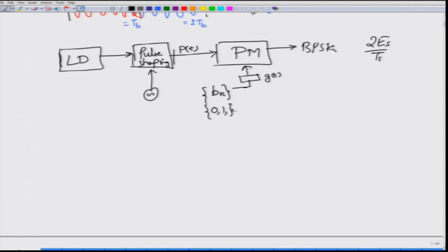Now, with the BPSK signal you are able to transmit one bit for one symbol. So, it occupies a certain bandwidth. We will come back to the bandwidth calculation in terms of power spectral density after some time, but if you look at the power spectral density, which has a certain width corresponding to the bandwidth of this particular modulation technique, you will see that for that given bandwidth you are able to transmit one bit for every symbol that you transmit.